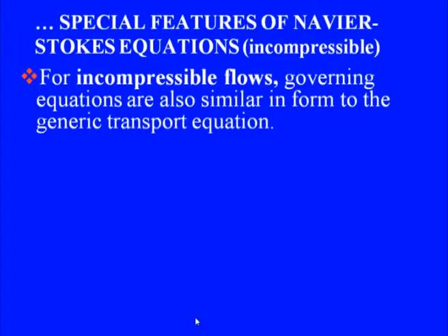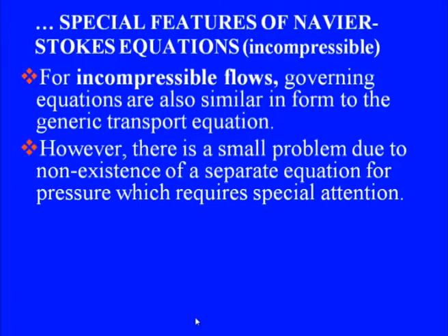Of course, that will involve huge amount of investment in terms of the computational time. Next, let us have a look at incompressible flows. For incompressible flows, again, the governing equations are in the form similar to the generic transport equation, with one difference here, that in continuity equation what happens is, it's not a dominant equation in terms of density.